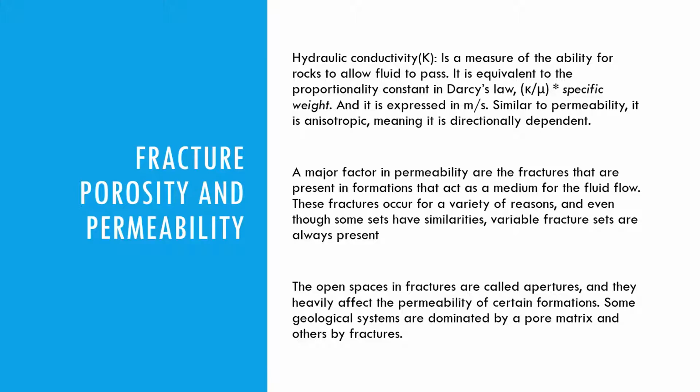It's only natural that hydraulic conductivity would be anisotropic because it's dependent on permeability, which also in nature is anisotropic. A major factor in permeability are the fractures that are present in formations that act as a medium for the fluid flow. These fractures occur for a variety of reasons, and even though some sets have similarities, variable fracture sets are always present.